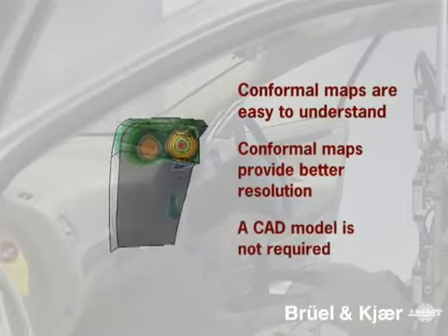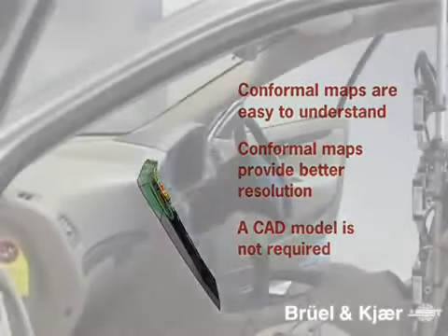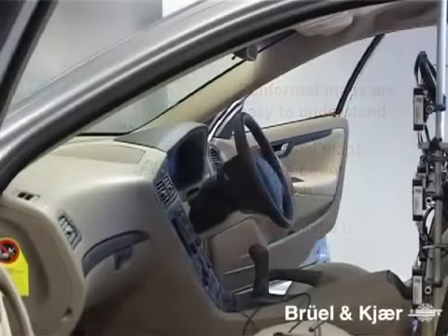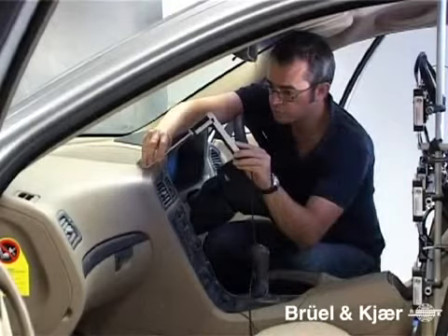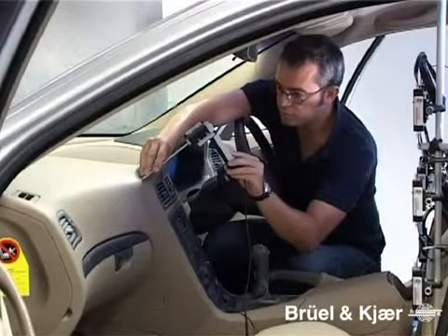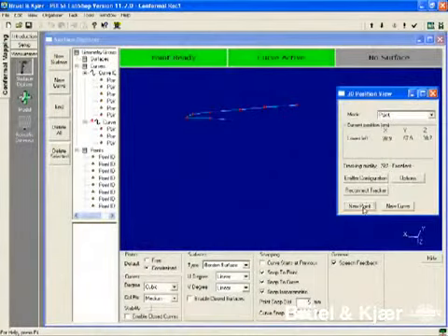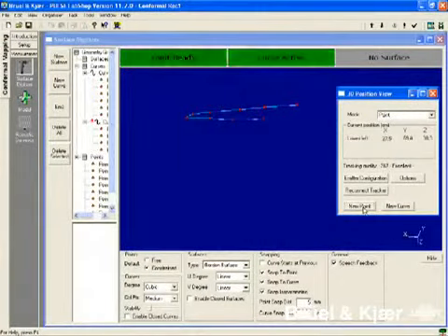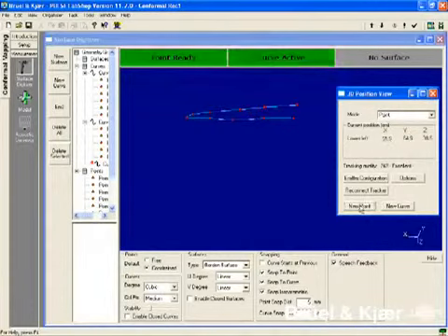The source geometry may come from an existing CAD model of the surface or digitized using a positioning system, as we'll do here. During digitizing, points are collected on the surface of the object we want to investigate. The model may be as coarse or as detailed as required. The operator simply moves the pointer mounted on the array handle from point to point and collects its 3D coordinates. In this way, a complete set of points on the object is collected.